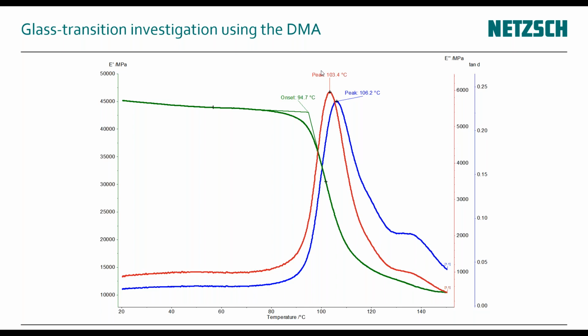Another question goes back to the comparison of DSC and DMA: if it's not possible to get more sensitive measurements for the DSC. And another question refers to sensitivity meaning dependency on the operator's skill. That is not true. The DMA, by the strength of the signal, if you look at the y-axis, our signal goes from 45,000 megapascal down to about 10,000 megapascal.